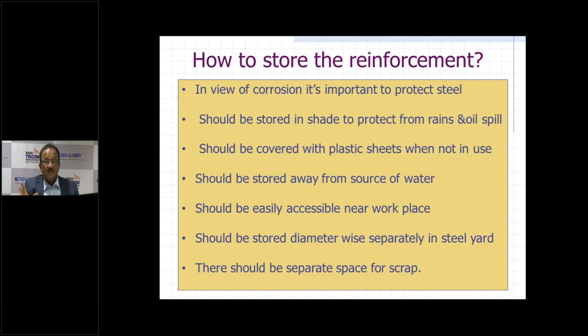Correct? Because when you cut the bars and use it for reinforcing purpose, you are bound to generate some scrap. So the scrap should be not scattered on the site haphazardly. It should be stored properly, and the separate space has to be designated for storing the scrap, so that it can be disposed of conveniently.